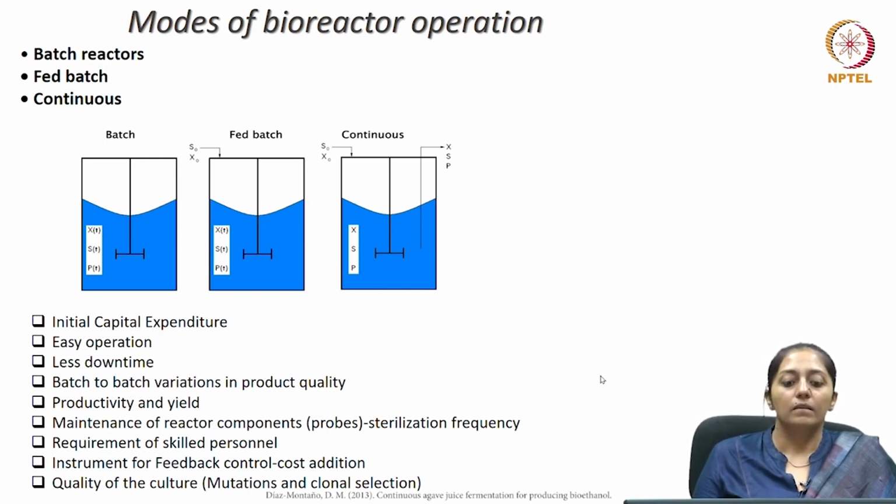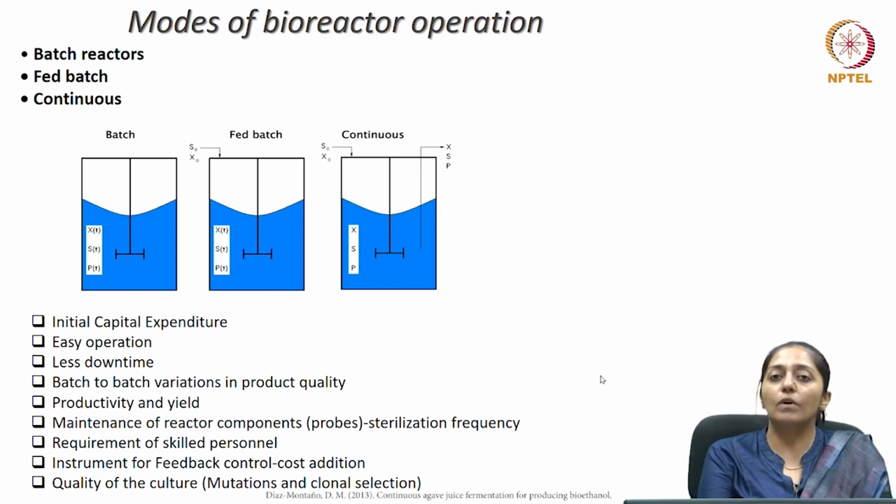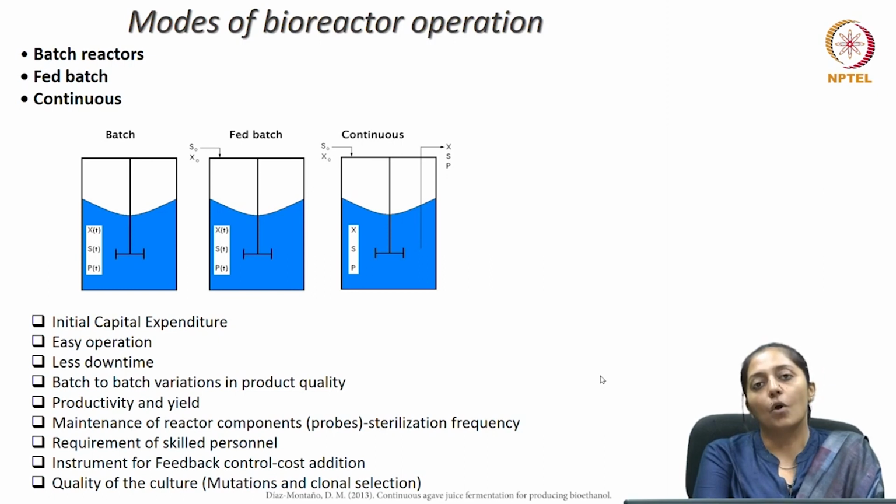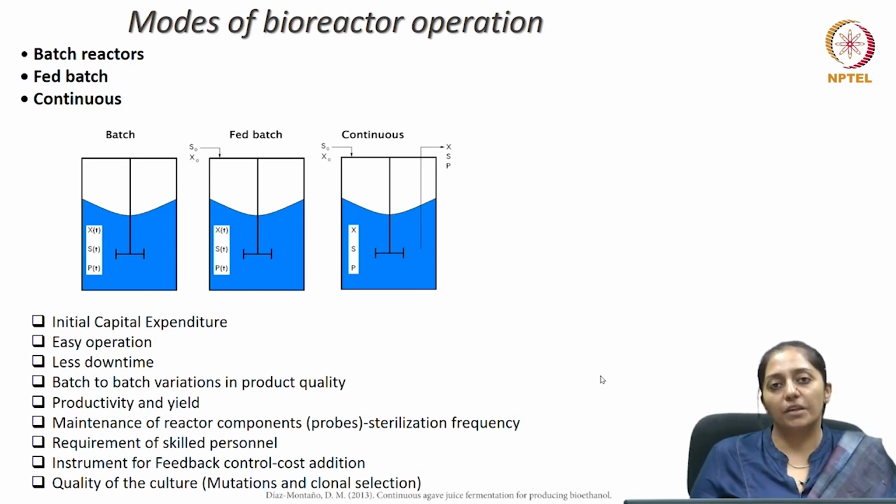While the middle schematic is a fed batch mode of cultivation in which you can clearly see a feed coming inside the reactor from the left hand side. But nothing is going outside the reactor. So this is classed under fed batch mode of cultivation. Because there is no continuous stream coming outside the reactor, the volume keeps on changing with time.